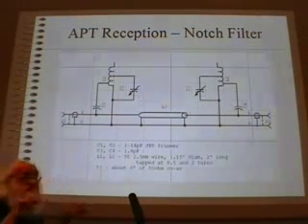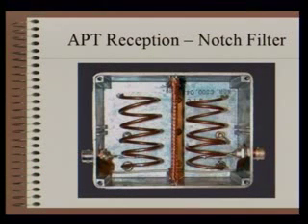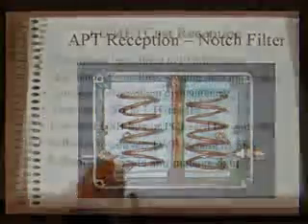It's not acting as a peak, it's actually acting as a notch. It sucks out energy, and that's a sort of physical implementation of it. So the difficulty being you can't use a quarter wave stub or something like that because the interference is about 600 kilohertz away. So you're either into the cavity filters that you use for a repeater or something similar like that. That doesn't tend to drift too much with temperature being in the shaft, which is quite nice.